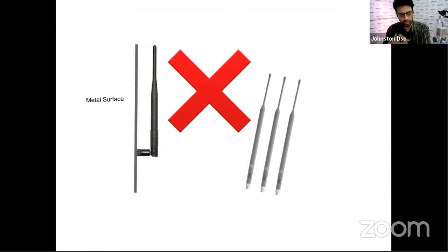And then you'll think, why am I not getting signal on stage? Signal is dropping. You'll probably turn the box. Even after you turn the box towards the stage, you're still getting dropouts. Why? It's not because of the orientation of the box or anything. It's just because the antennas are very close to each other. Input antennas, output antennas, all close to each other. So in this case, you need to go and buy remotely mountable antennas. Most of these antennas are not remote mountable. If they are remote mountable, it will be mentioned.